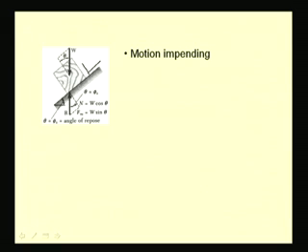So, a frictional force develops which acts against this force, which is this Fm. So, for the limiting case we have Fm equal to W sin theta and the normal reaction equal to W cos theta.